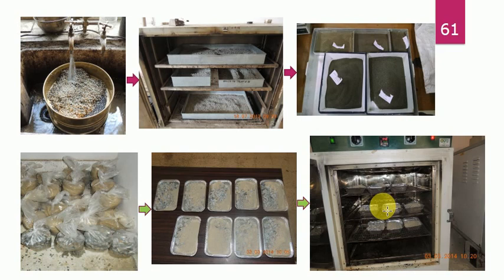So here the initial step is heating the required weight of the aggregate to the desired temperature. Then heating of bitumen is required, the weight of the bituminous binder to the specified temperature, for the different trial binder contents that are selected.